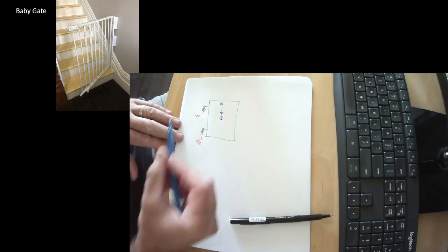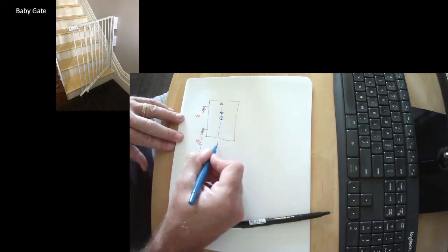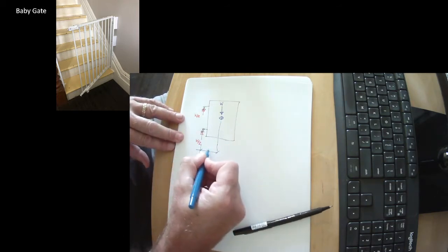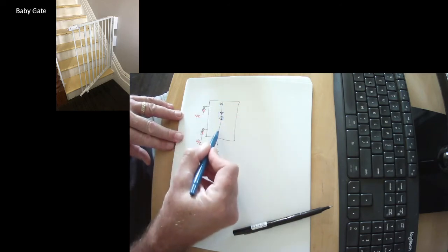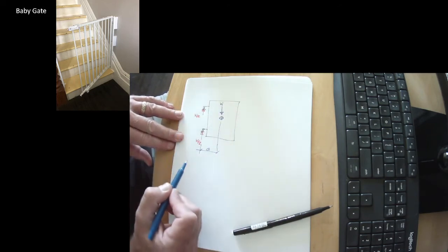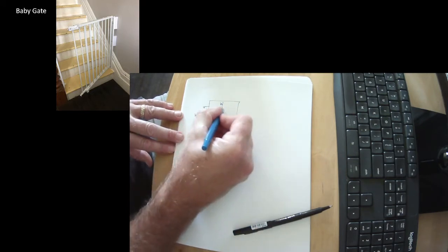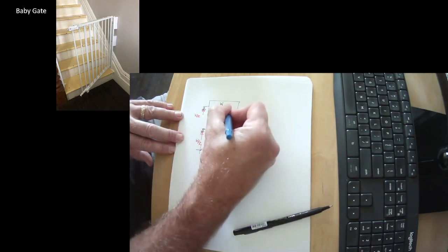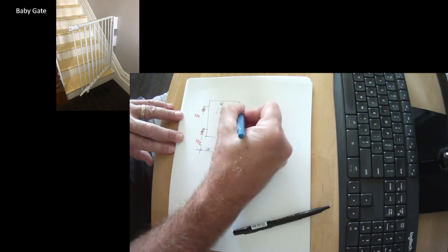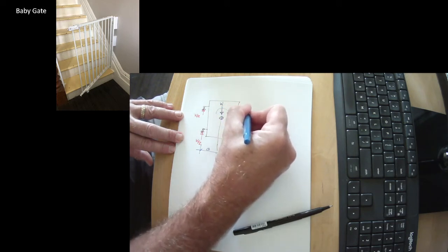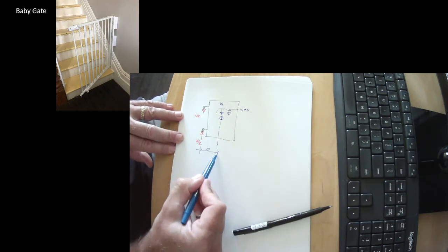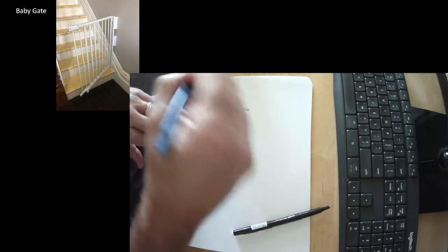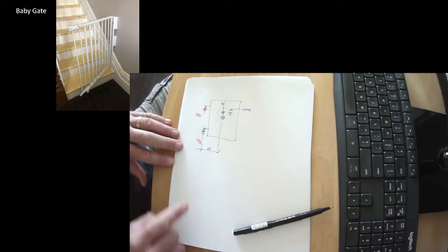Okay, so what we can see though is we have this residual eccentricity, that the center of load down is not aligned with the center of resistance up, which is tending to make it want to rotate. By the way, the magnitude of the force trying to make it rotate, the moment, is equal to W times E. The weight times that eccentricity is the magnitude of the rotating force. So that is not an equilibrium.